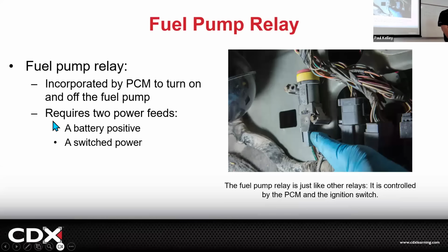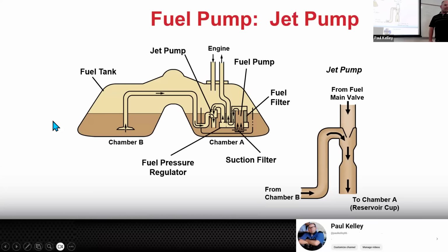Okay, and then if we were to get into, I think we're probably pretty good on there, but I believe I made a note about, it might come up again, but in the case that I missed my note, there was something I wanted to say. When we pull fuel right here, we're going to pull fuel up and we're going to send it out the pump. The thing is, when you shut the engine off, the fuel pump and tank sit low. So you could have all this fuel drain back, right? It'll drain back and go into the tank. What's going to happen when you go to start it next time if it all drains back?